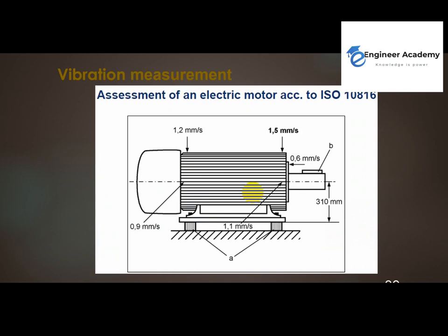Then the question here: how can we make a reference when I'm saying this vibration is good, and when I'm saying this vibration is not good? According to what? We have many references. One of them is the ISO standard 10816.